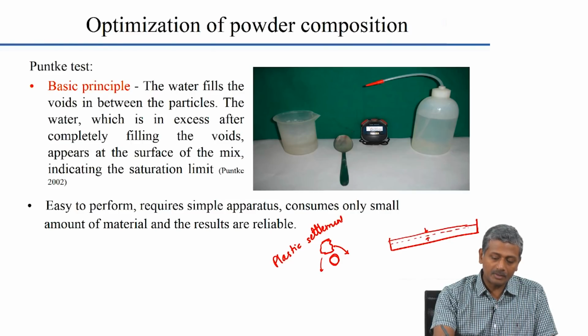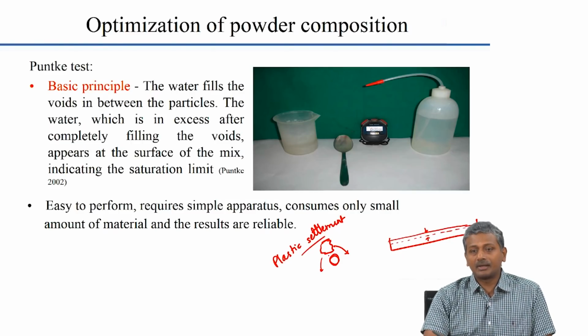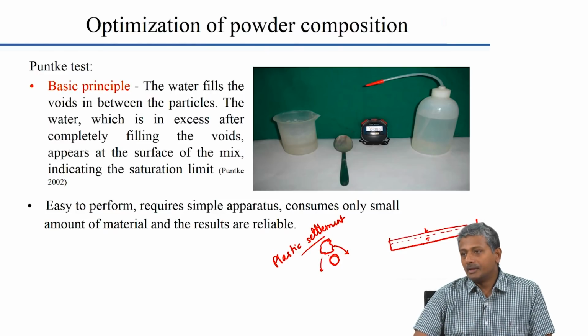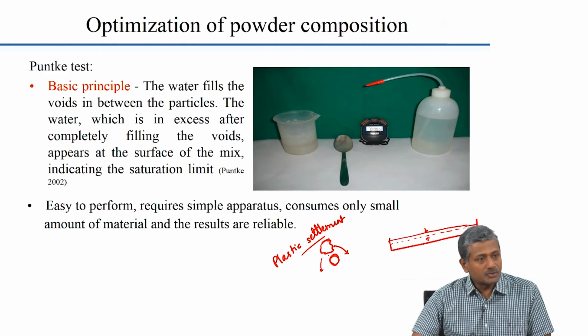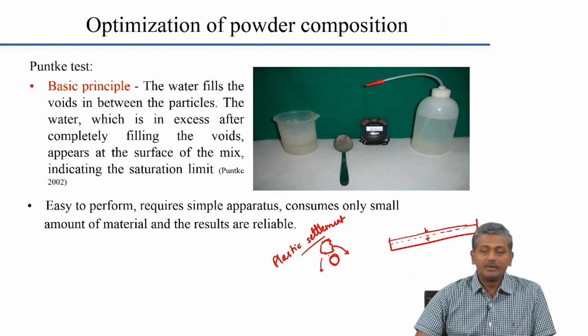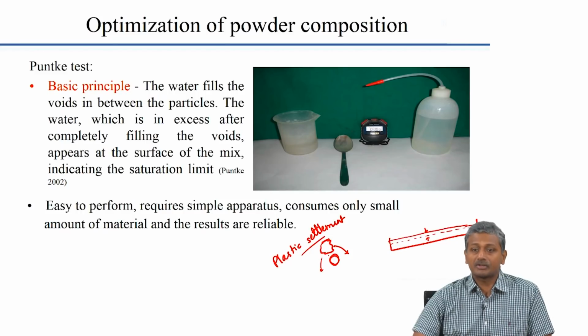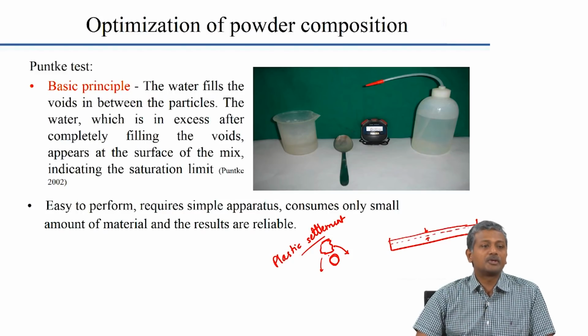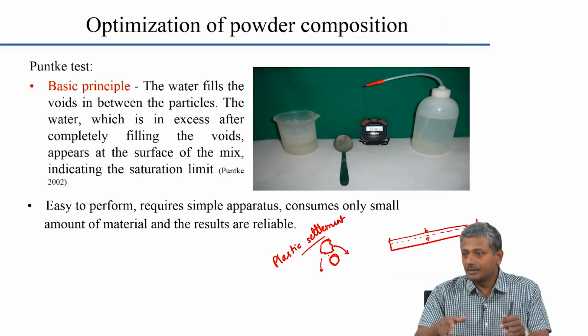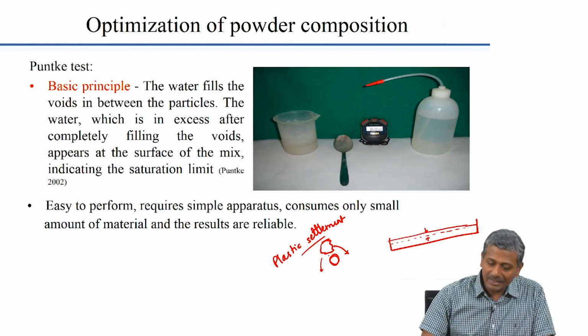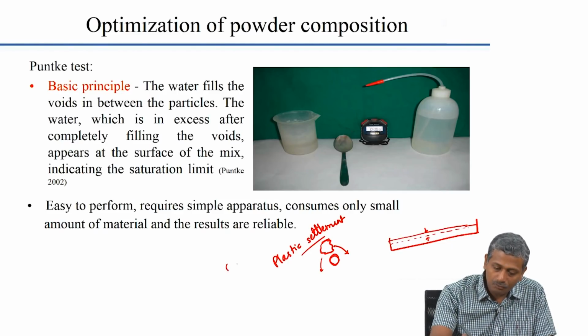So, if you have very high flowability of your SCC, you will get what is also known as plastic settlement. And this plastic settlement can lead to some cracks occurring right on top of the reinforcement. Indeed, when people started using SCC, when they produced high flow SCC and started applying it for slab, one of the primary problems that they saw was plastic settlement cracking. You would actually see the layout of the reinforcement on top because the concrete had started settling around the reinforcement. So, you started getting cracks just on top of the reinforcement.